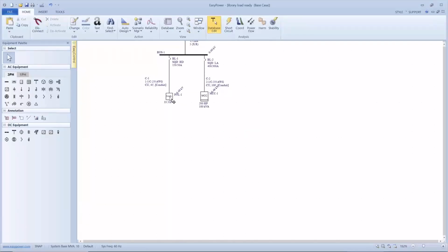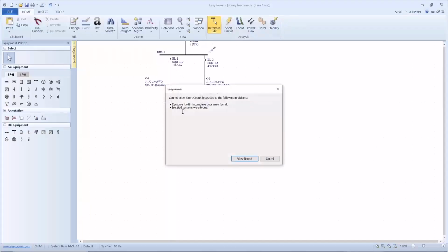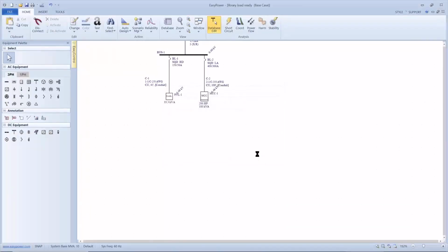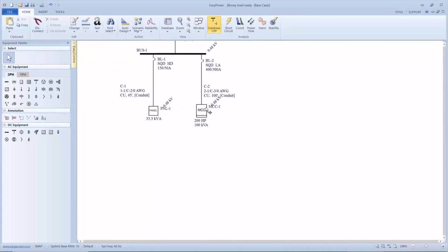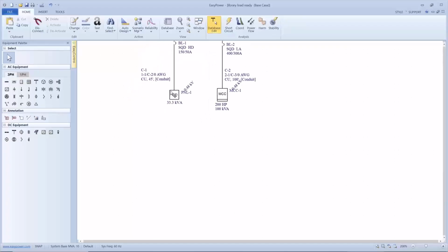One of the disadvantages, that's a good point, Chuck, thanks, of using the icon is, when we calculate incident energy, it's showing the calculations for the main bus of the panel and the MCC itself. And so very often it's going to exclude the main, and that's why I used the main lug only. If we connect a load downstream so we can see what the distributed incident energy is, or for whatever reason we want to do that, let's go ahead and set up a two-winding transformer.